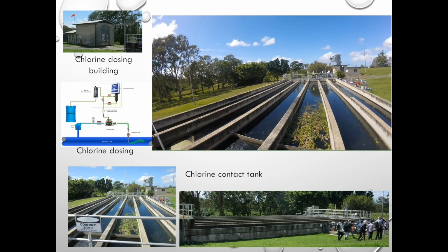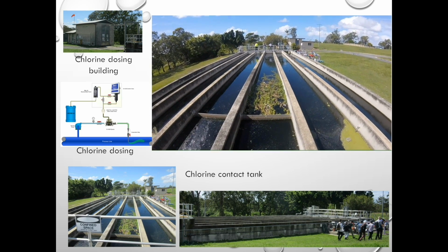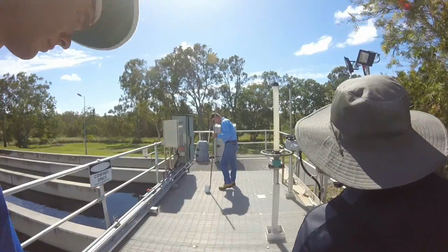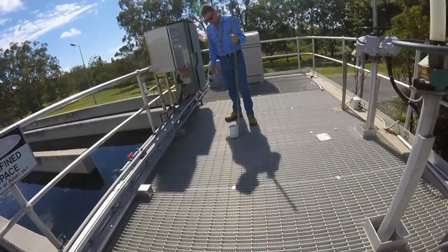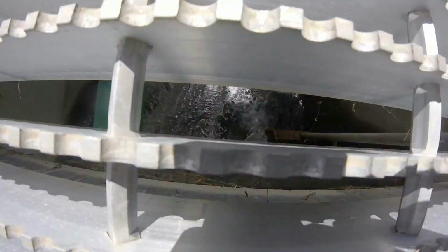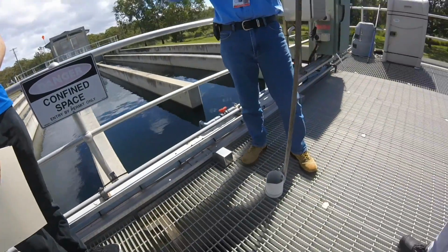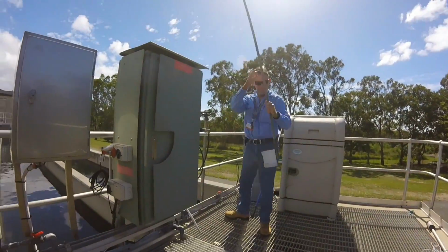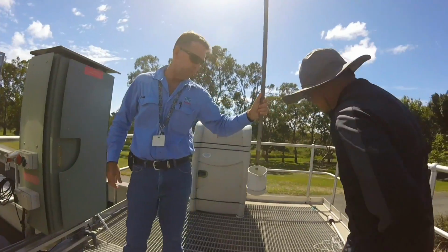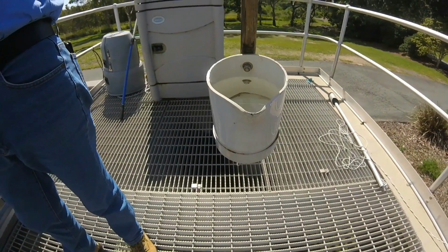Cleveland's chlorination design requires 45 to 60 minutes of chlorine contact time. After the water has steadily flowed through the contact tank, an automated dose of SBS, sodium bisulfite, is added to the chlorinated water for instant dechlorination. Thus, chlorine is removed and the final effluent is a slightly salty water, which can be safely disposed into the environment, as it no longer poses a risk of killing essential biota in the natural waterways.